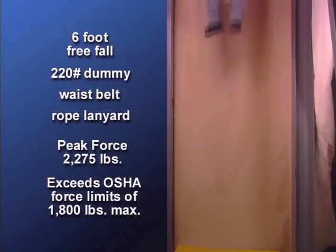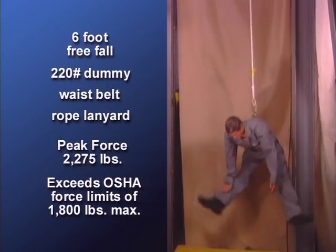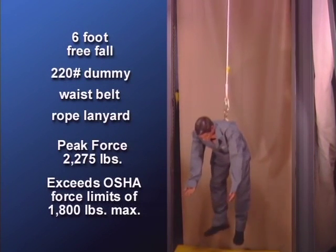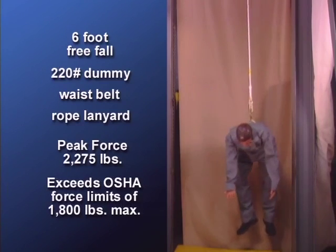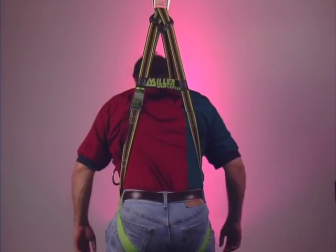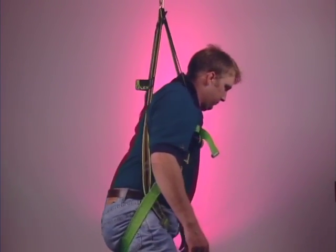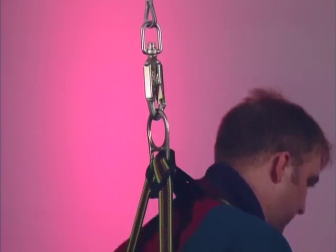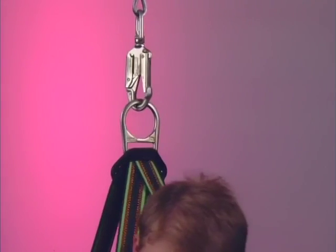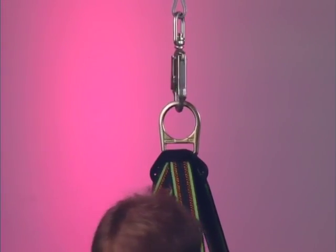In this drop test, a dummy is dropped into a body belt. Note how the fall forces were concentrated on the abdomen. Such forces concentrated on the abdomen could cause serious internal injuries. In addition to optimum force distribution, a full-body harness keeps the worker suspended upright while awaiting rescue. This is due to the sliding D-ring, which moves to the nape of the neck once a fall occurs. This allows the worker to remain as comfortable as possible until a rescue team arrives.